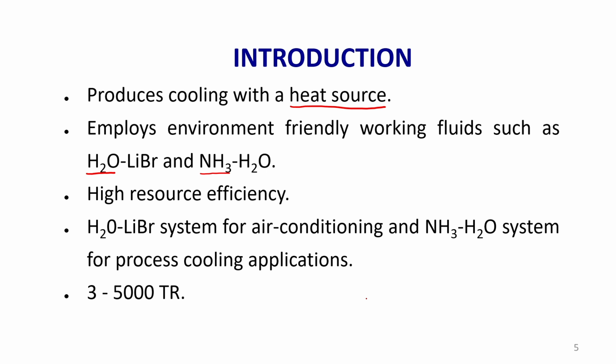Normally these water lithium bromide systems are used for air conditioning applications, because water is the refrigerant. So the freezing point of water is 0 degree centigrade. So we cannot use water below this for sub-zero or low temperature applications, that is negative temperature applications. So it is used for air conditioning. Of course, if you add some brine to this, the freezing point reduces. So that is what is done in the chilled water system. But if you use water as such, it is not recommended to use below 3 degree or 2 degree, because it reaches the freezing point.